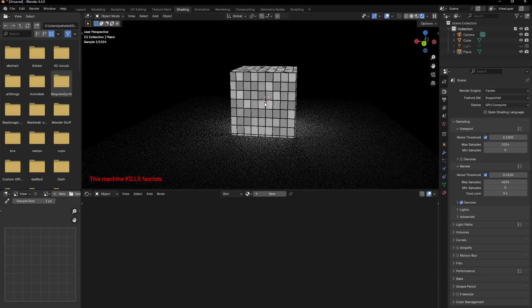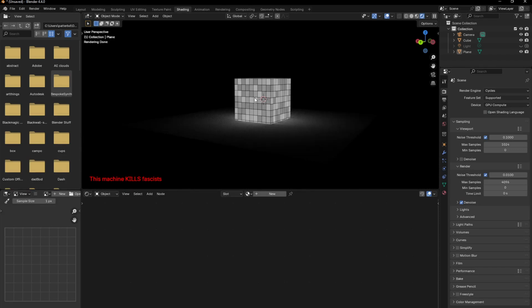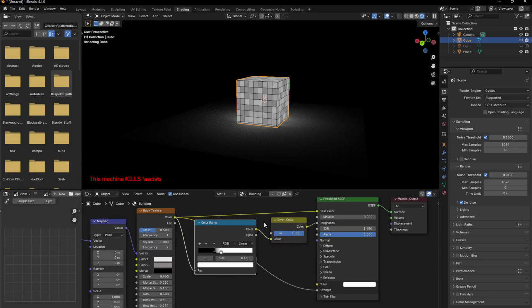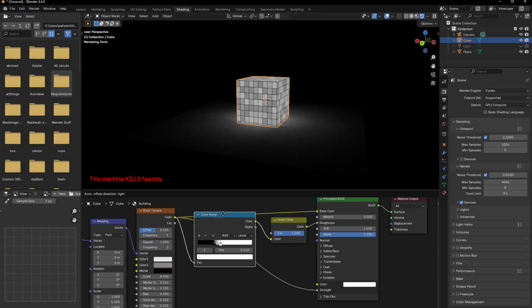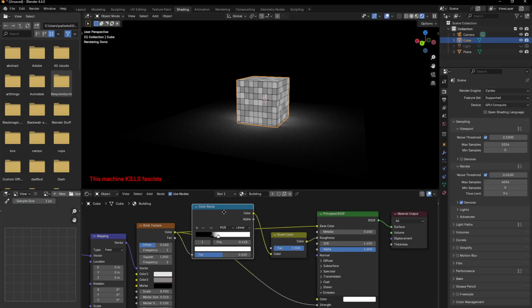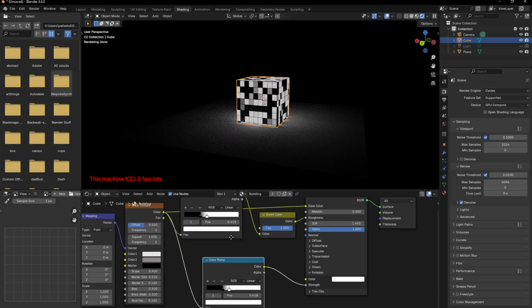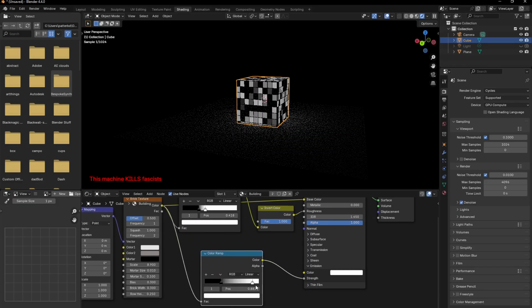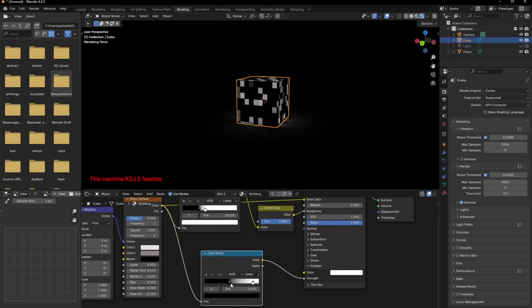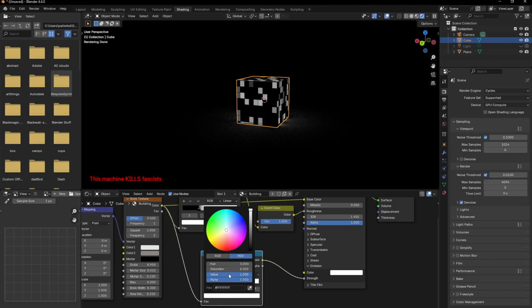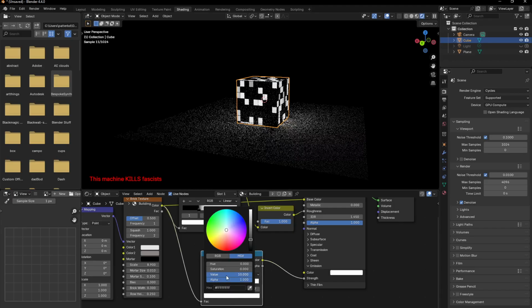If I don't want everything to be giving off light, if I want it to be a little bit more random, I'll select that again, and I can just copy this color ramp with Shift D. I can adjust these signals so that only the highest signal will be the glowing windows. If I want those windows to be brighter, I can select this stop and make it brighter by typing in a larger number, like 10.